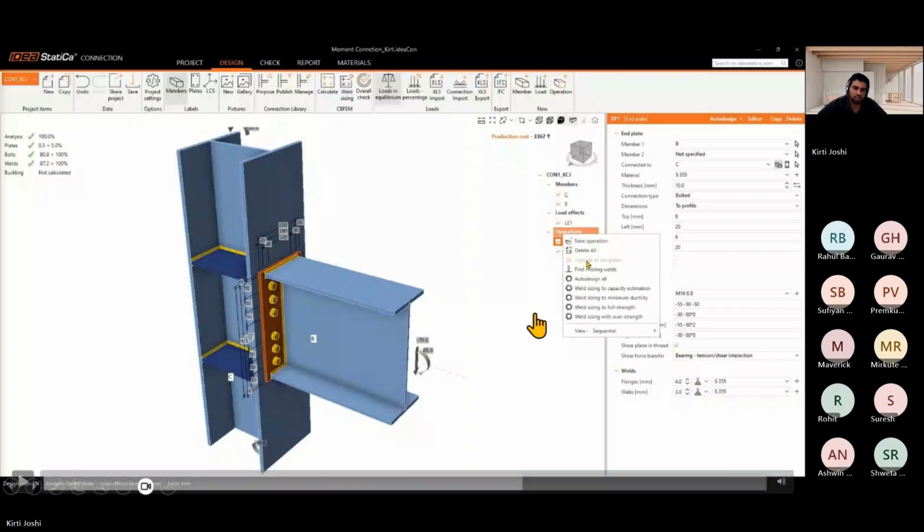You can click on any of the options to optimize the design. Right now, I clicked on one of the options, and the production cost has been displayed accordingly. For example, if you want to reduce the stiffener, it has reduced my production cost overall. Once you reduce the thickness from 16 to 14 also, it will reduce the production cost displayed on the screen.